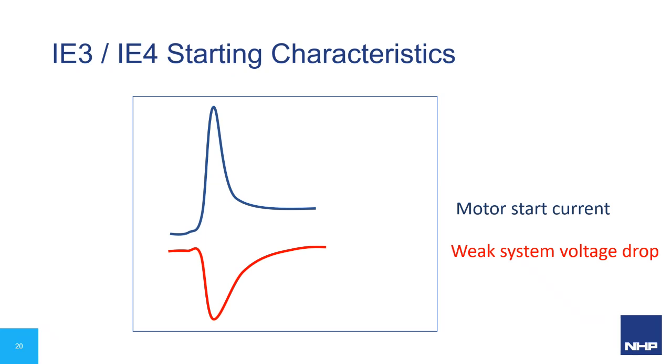Now, during a motor start, here's another issue. During the motor start, an extremely high transient current spike can cause the voltage in a weak or marginal supply system to drop away to potentially very low levels. Now, in certain ranges of contactors, the voltage drop may cause a coil fluctuation, and this can cause the contactor coil to reduce the closing force on the contacts. So we see here a motor start current and spike in the current.